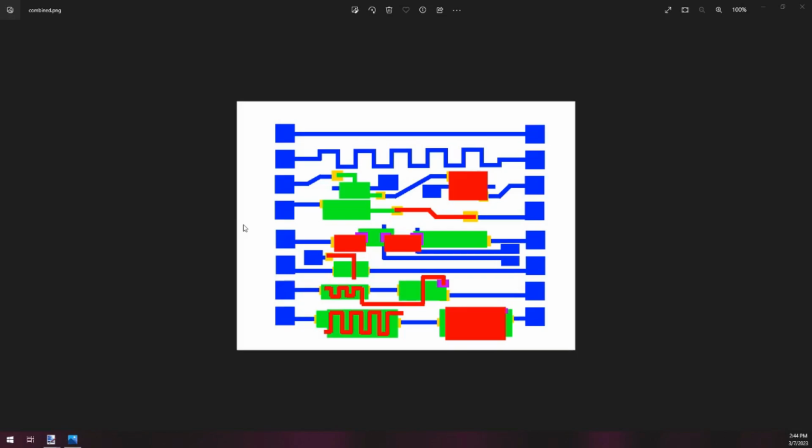Now there's two exceptions to this rule, and the first is at the vias. Any via has to have some metal underneath it, otherwise the polysilicon layer or the diffusion layer cannot connect to it. So there is a bit of logic there to check for that sort of condition, which is why when I clicked on these circuits, the via in the middle was never selected. The second condition is the transistors.